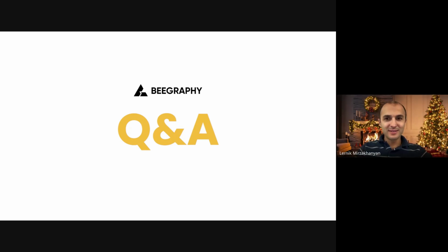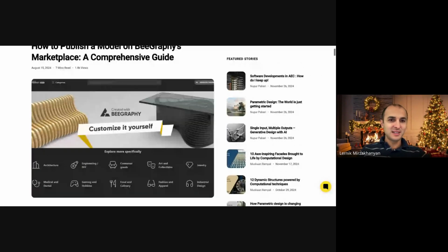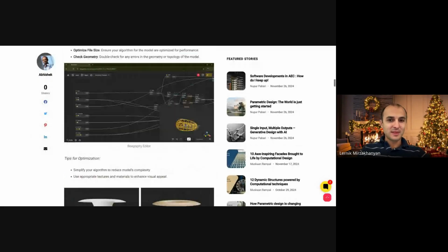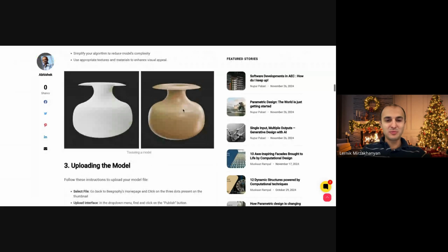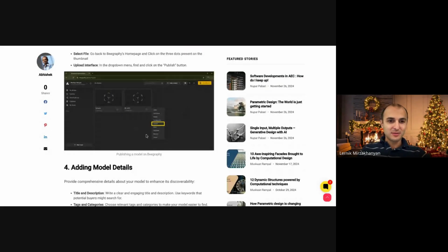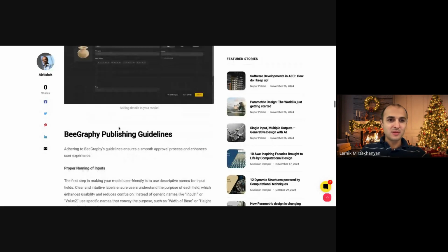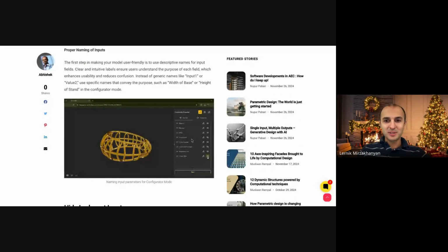I just want to answer kind of two questions. One was this one. So if you Google BeeGraphy how to publish, you will find this blog post about how to publish in the BeeGraphy marketplace. It's quite detailed, step by step, related to what you can do, how you can do this, how to apply textures, how to then publish, what kind of tags we need, how you can rename the inputs, hide, change the sequence.